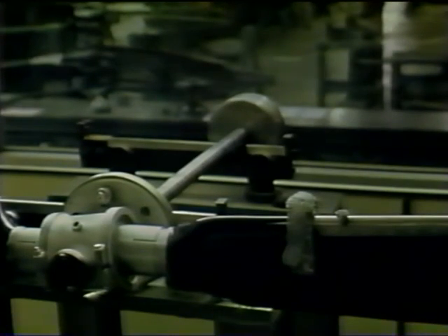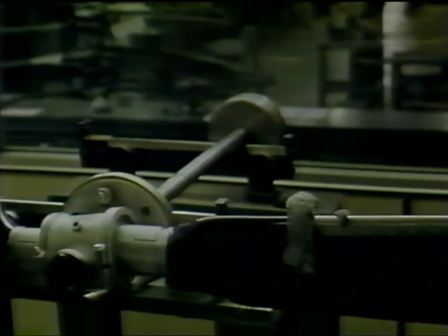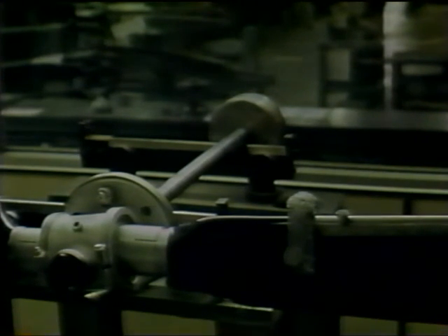After final assembly, constant speed propellers are checked for proper operation by connecting them to a pneumatic test stand and cycling the propeller through its blade angle range. The assembled propeller is checked for static balance using this knife-edge device. Small amounts of lead wool or steel weights are placed in the hub areas of each blade to bring about perfect balance, both horizontal and vertical.